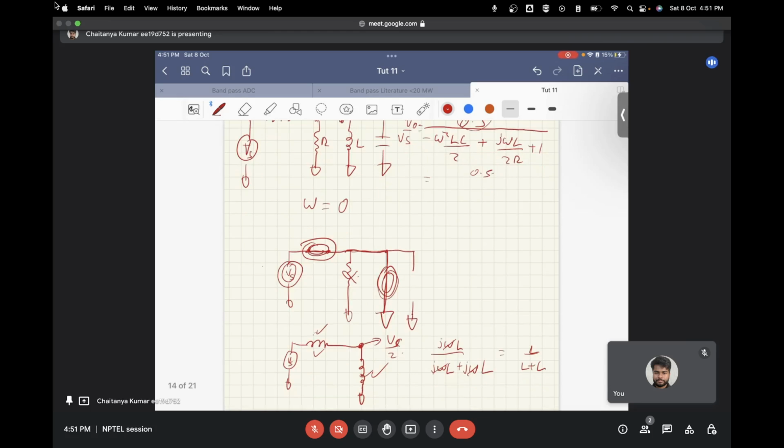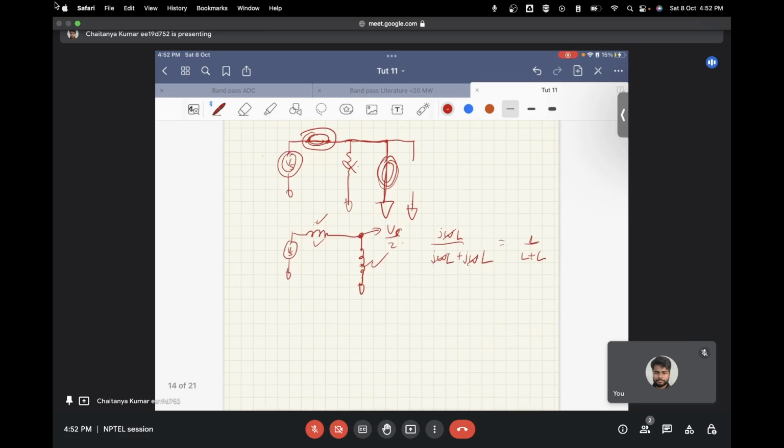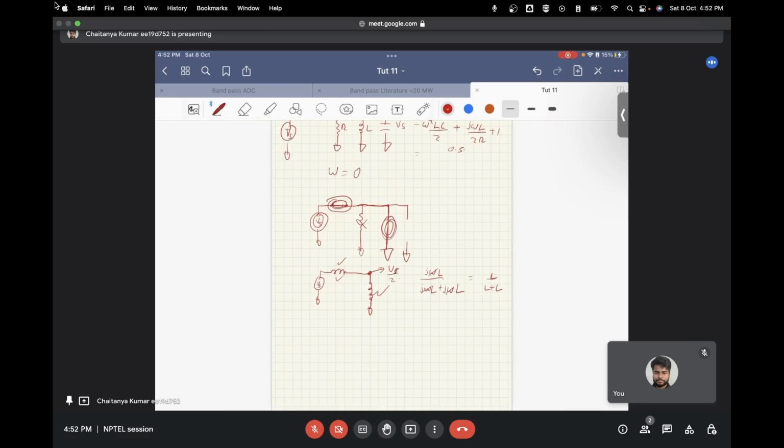In this case, the mistake was that the source impedance and the load impedance both are approaching zero, so you cannot neglect one compared to the other, because since both impedances are small, their values are comparable. So the resistor divider or impedance divider still holds.